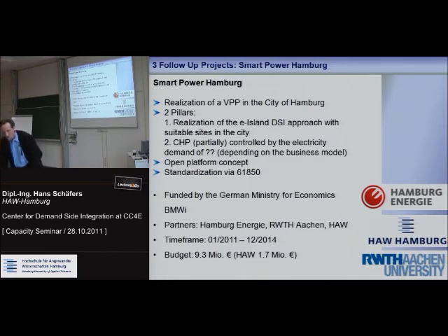But if I only look at my schedule and my deviation without looking at the system, then I might rule out this deviation just because I intend to rule out all my deviations. It might be wrong. At the moment, with my deviation, I'm earning money because the electricity system itself is long, and I get it basically for free. So it's important to actually look at the system, at least at the net frequency, to find out, shall I rule out my deviation or shall I not?